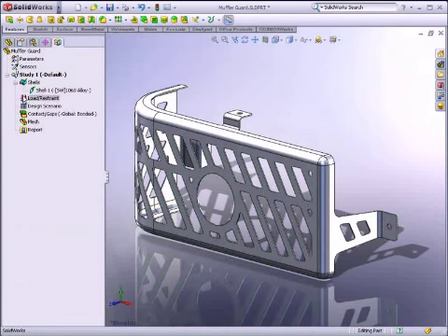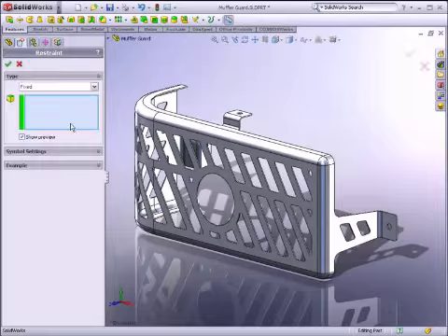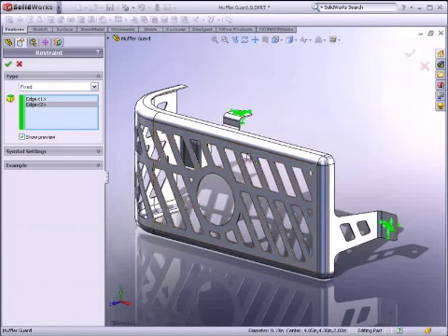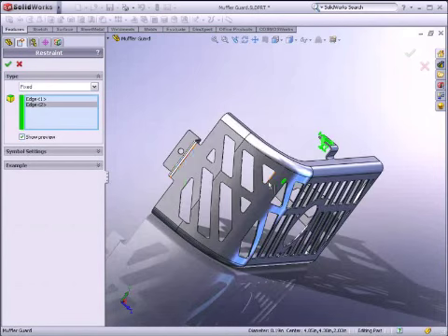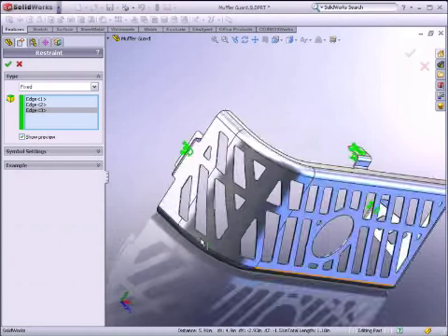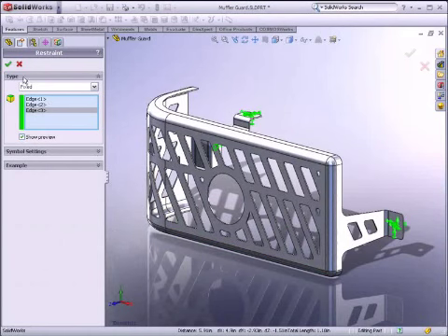However, we can easily create further studies in SolidWorks Simulation by selecting material from a vast library to pursue alternative design solutions. The guard is mounted using 3 bolts. We will simulate the effects of those bolts using restraints on the 3 mounting hole faces.